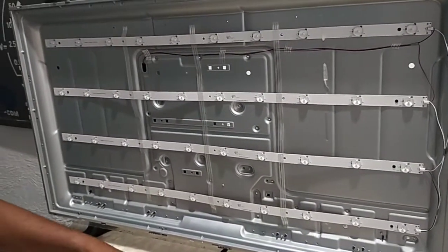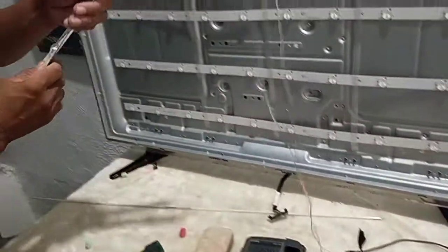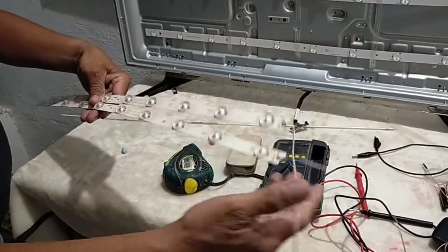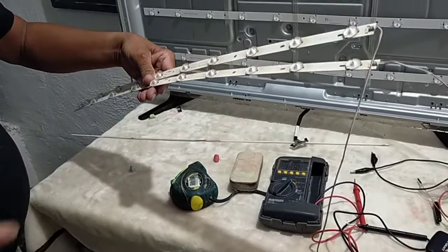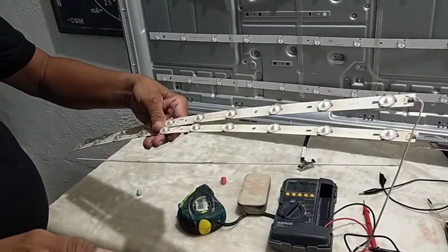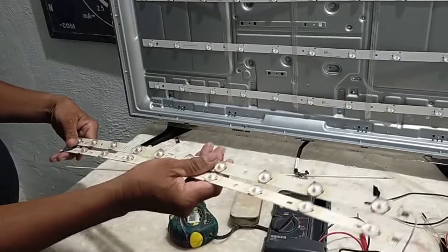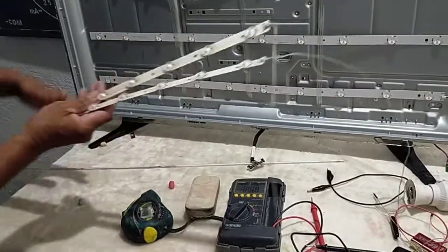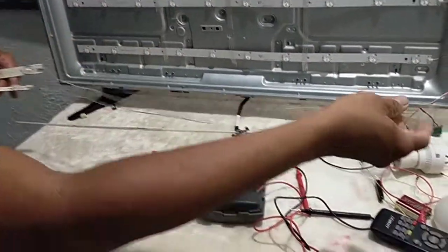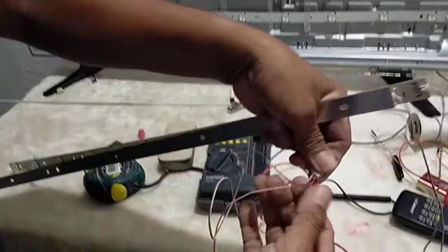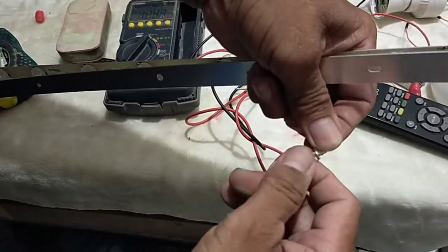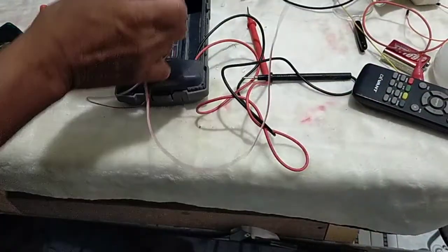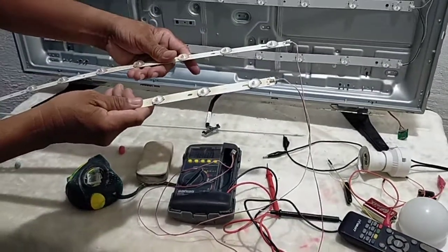Unlike this backlight here, this backlight, which is also made of LED, is applied to a 32 inch digital TV. Usually it is a Devant. So there are 2 strips with 10 LEDs in series each. The 2 strips are actually connected in parallel. We have here, see? The red and the red are connected together. The white and the white are connected together. In other words, the 2 strips are connected in parallel.